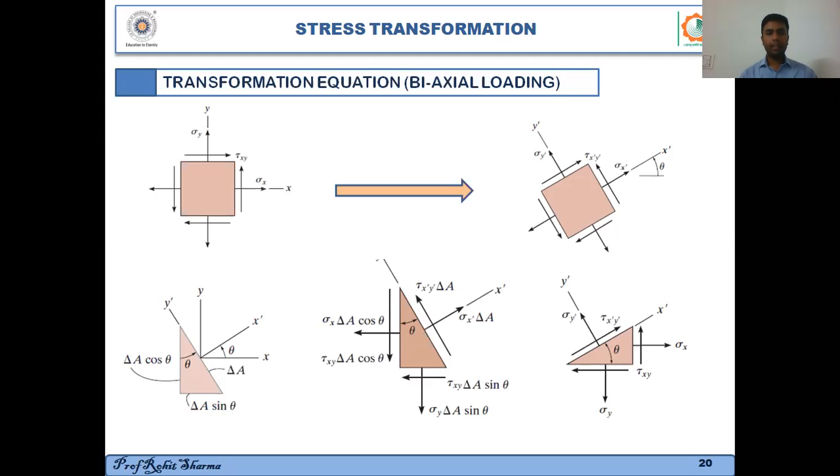But I'd like to reiterate that if this is your initial stress block and you rotate it by some angle θ, then the initial stress σx on this face will change to σx', the initial stress σy on this face will change to σy', and similarly τxy will change to τx'y'.